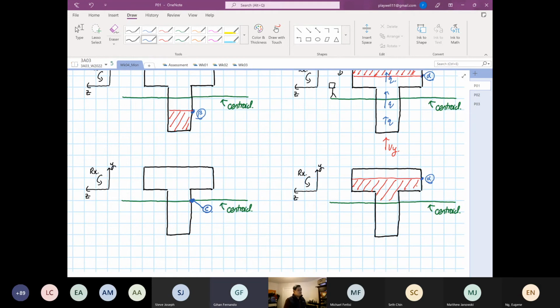Would either one be okay? Because neither place where we take Q would cross the centroid. Yeah, it does not matter, because you can take it from the top. You're absolutely right. Now, Jihad, why do you make that statement? Oh, because point C is directly on the centroid, so whether we take it from the top or the bottom, it's not going to cross over.